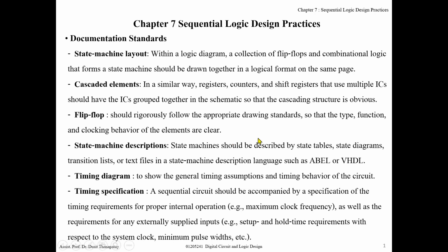maybe using a state output table, state diagram, or transition list. And sometimes maybe use a state machine description language such as ABEL or VHDL or Verilog, something like that. And a timing diagram is also very important for the design.